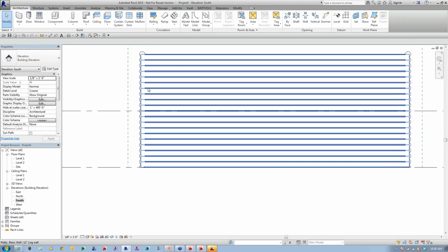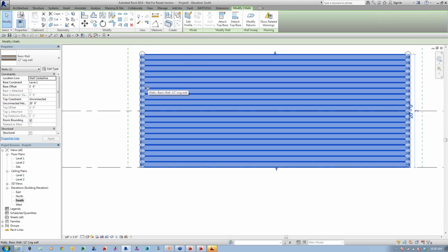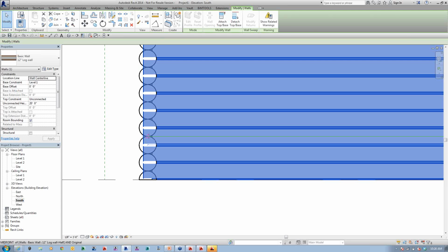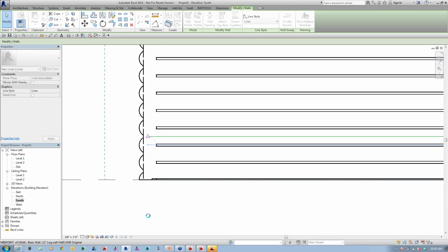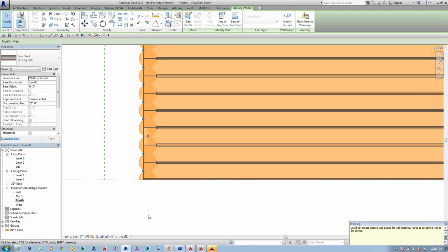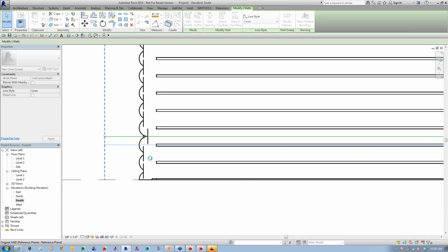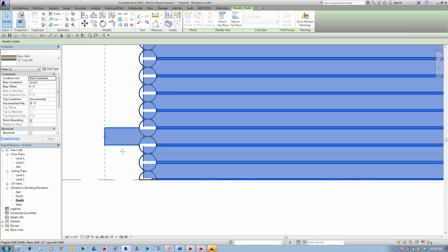Okay. Then I'm going to come inside. I'm going to select that wall. We're going to see we have all these little grips. See all these little blue bubbles at the very left and right side? Well, those are the sweeps. So if you're looking to do a blind saddle, you might have to bury this inside the wall and put that sweep inside, and it'll bury it halfway in. But if we're going to do a saddle and bring that out all the way, I'll just drag all these over. Yes, it's kind of a manual process. That's the part I've got it to right now.